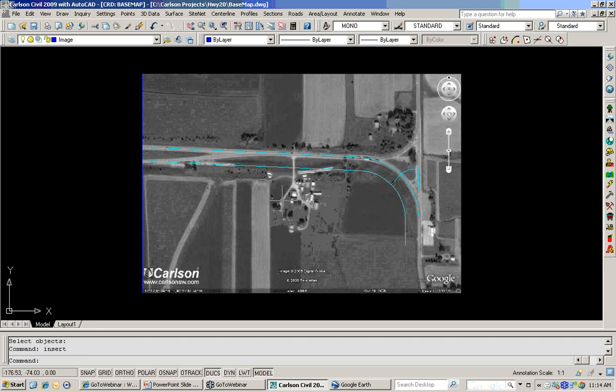So what we've got right now is our westbound lane that is already existing. We've got a proposed eastbound lane that we will take through here, and if I wanted to, I could continue this on to the south, but for today's discussion, I'm really focused on this area. We've got State Route 84 here on the east, a little connector road that I've put in, and also a driveway that served this residence down towards the south of my project site. All of these will be used in a little bit inside of our RoadNet application as we go through and start to lay out all these different intersections and design scenarios.